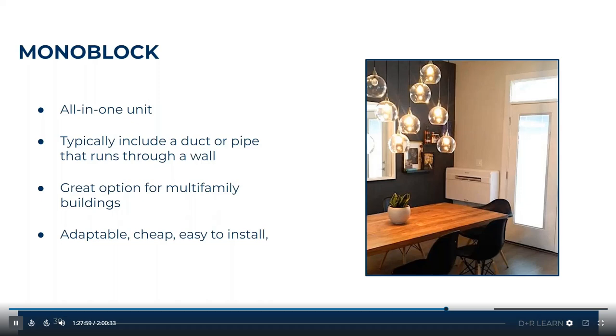And the reason I'll agree with that is if you don't have adequate airflow inside of your space where you have a mini split system installed, yes, that definitely could be an issue. They say for ventilation purposes. See, the thing is with mini splits, you have to have an alternate source of airflow. It's not like your typical hydronic system where you have fresh air intake coming from an air handler system that is required by law to be open 10% at the very minimum.